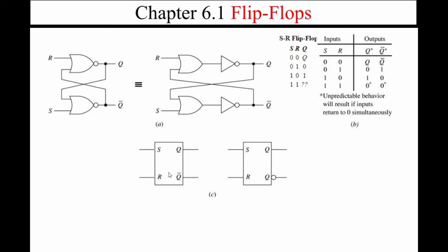So in summary, we don't really ever build flip-flops out of these NOR gates or NAND gates. Even inside the FPGA, there's going to be special circuitry that doesn't look like this, that's going to try to minimize the craziness of the SR flip-flop. Now, when we go to the other types of flip-flops, you're going to see that they solve this problem in different ways than Latches putting question marks right here.